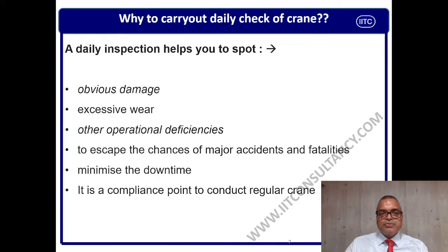So guys, now why carry out daily checks of your crane? You can take 5 seconds to try to find your answer as to why daily inspection is required. To summarize, daily inspections are required to spot obvious damage in any part of your crane, the safety equipment of the crane, or equipment of various operational parameters.